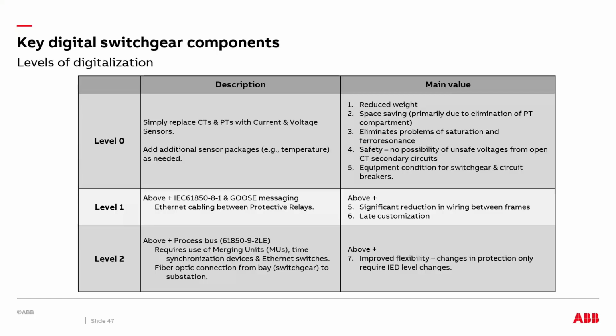IEC 61850-8-1 also has GOOSE messaging. GOOSE is Generic Object Oriented Substation Event, and the operation time is less than 10 milliseconds for distribution systems as per the standards required.